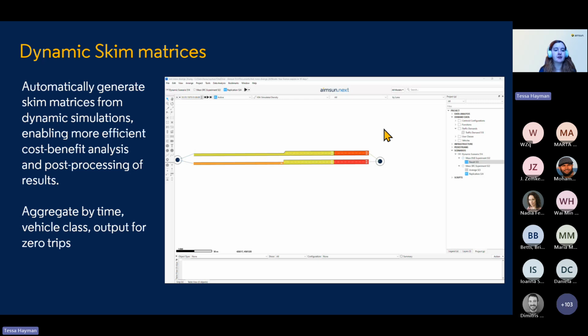You can also process this inside Aimsun Next. So here I'm going to filter by trips and a time interval with cars. And you can see I've generated a matrix with a standardized naming system that you could link to whichever thing you wish to use.